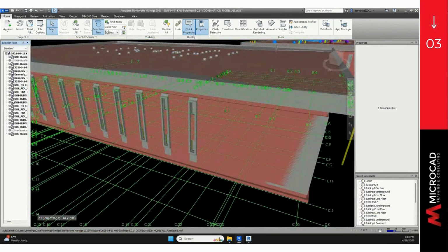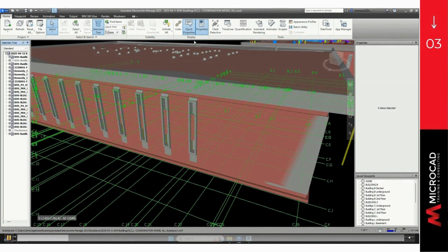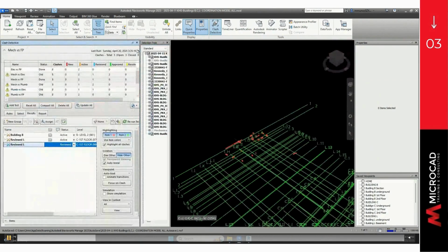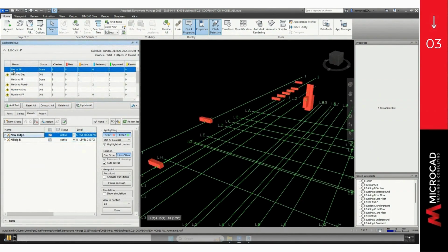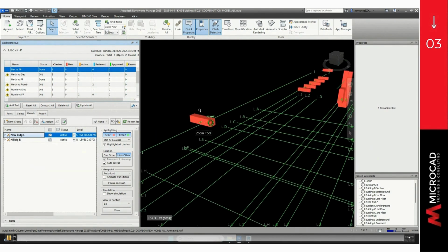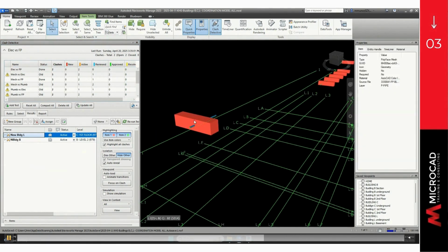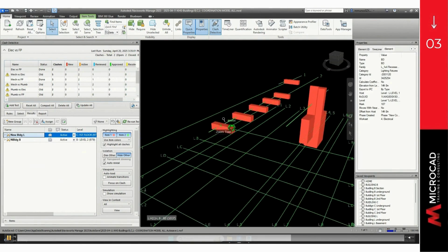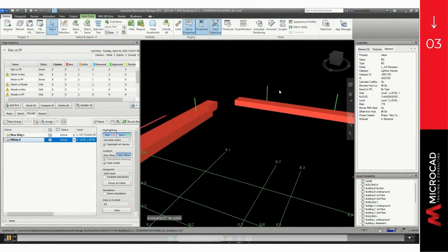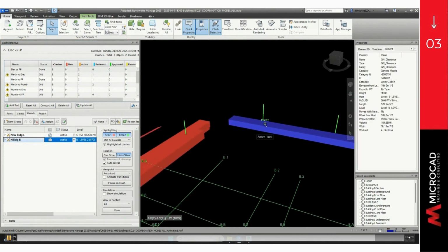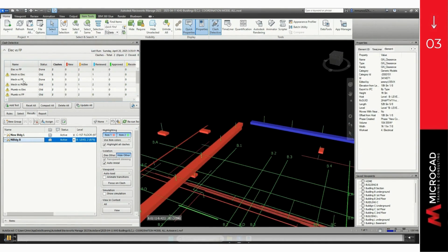So another great tool that Navisworks offers is the clash detection option. Over here, what we have to do is just have our Revit model exported to Navisworks. And once we have all our projects, we just have to run some tests to verify which elements are clashing with the other system elements. So this can be done between MEP models, structural models, architectural ones, and everything that you have in a BIM environment.